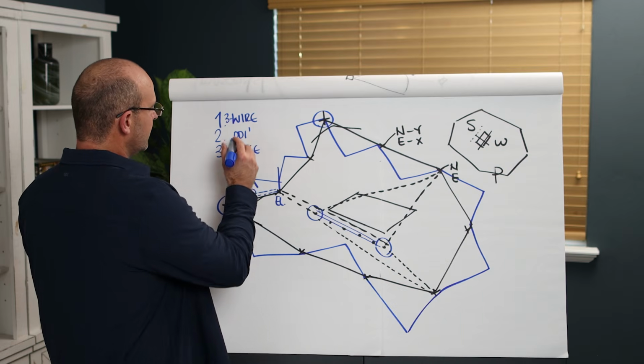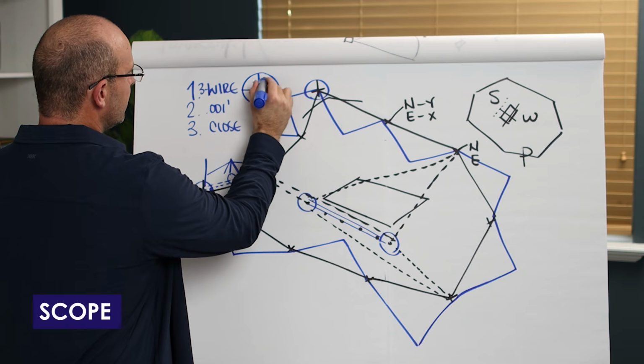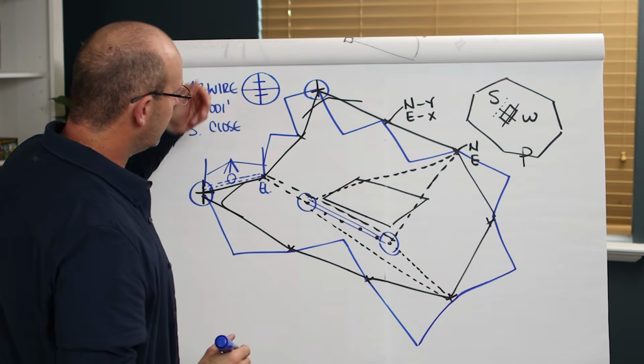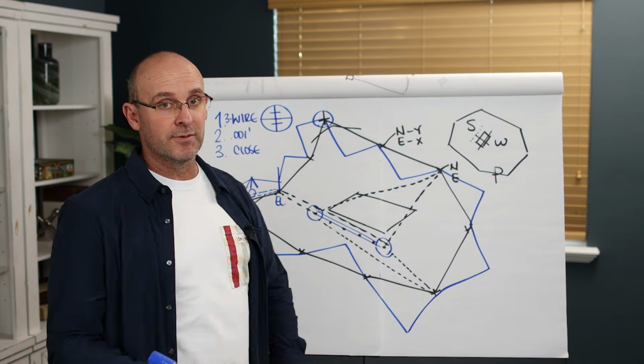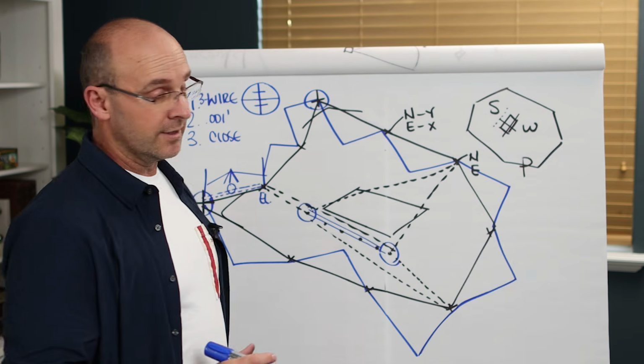Now here's the deal. When you're doing these shots, inside your scope, you will read your top number, your middle number, and your bottom number. Those other horizontal crosshairs are called stadia hairs. They're used for 2 different purposes. One is you can take the top reading minus the bottom multiplied by 100, and that's how far away from your rod you are, which is really cool how they did that.